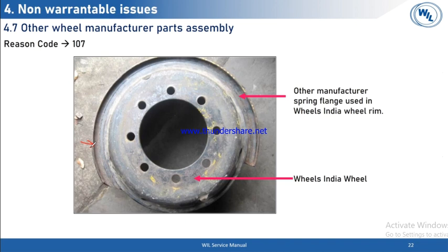So there are also some safety critical problems: the lock ring will come out during tire inflation, or if it has not come out, then there will be chances of cracking of the lock ring or the wheel rim because of the mismatch in profile. Each wheel rim manufacturer will have their own design and different kinds of profiles for wheel rims as well as the lock ring.